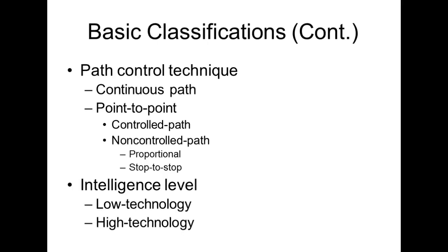Another thing is we have two classes of robots. All our robots are what we call point-to-point robots, which is point-to-point control, by far the most prevalent method of programming robots. So you saw a while ago in that simulation, how did I teach it? I just moved it to all the points. And then we specify how the robot does the points. We have a video I'll have to bring up. I hope I can find it.